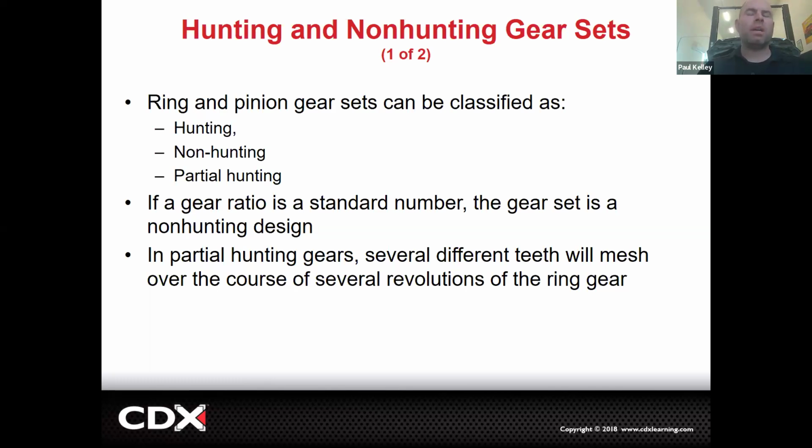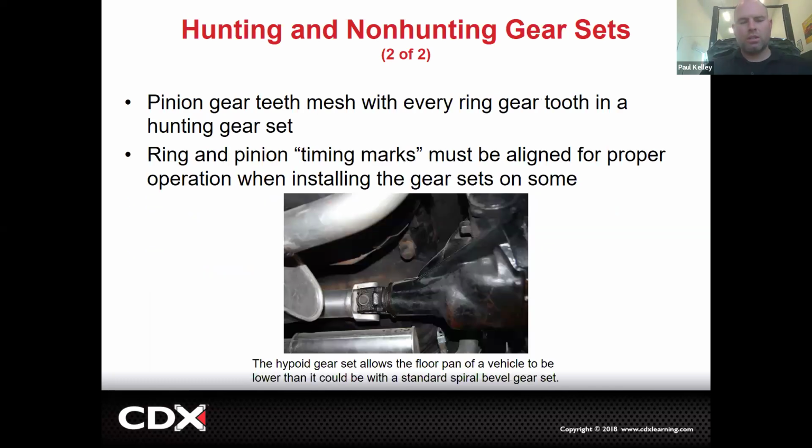So, is it the standard? Probably not, but some of the justification here, it says timing marks would be follow service info. Don't just yank it apart. Because if there were no marks, but you were supposed to make a mark, you would have missed your chance to make a mark before you pulled it apart. Okay, that's kind of the point.